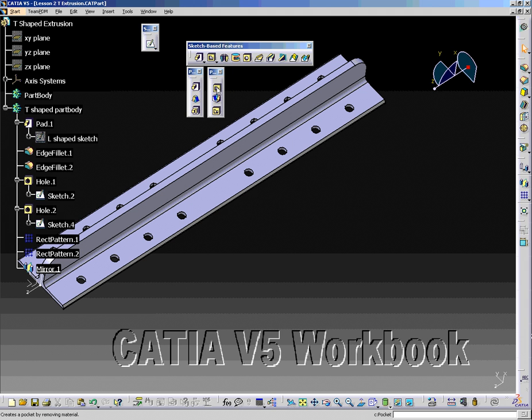The Pocket toolbar consists of the Pocket tool. This creates a pocket by removing material defined by the selected profile. Opposite of the Pad tool, it subtracts material. It requires an existing solid to subtract from.